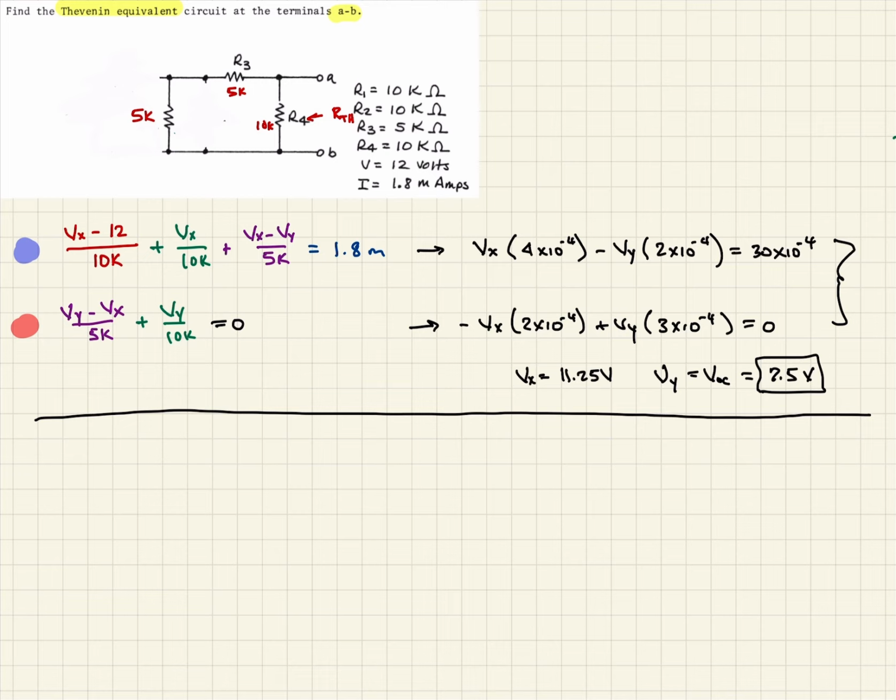And so now we have these two resistors here in series. So 5K and 5K, that'd be the same as just replacing with a 10K. Right, 5 and 5 is 10 when they're in series. So let's do that. So it's like this one's not here. We'll just short it out like this. And then this one here will now be a 10K.